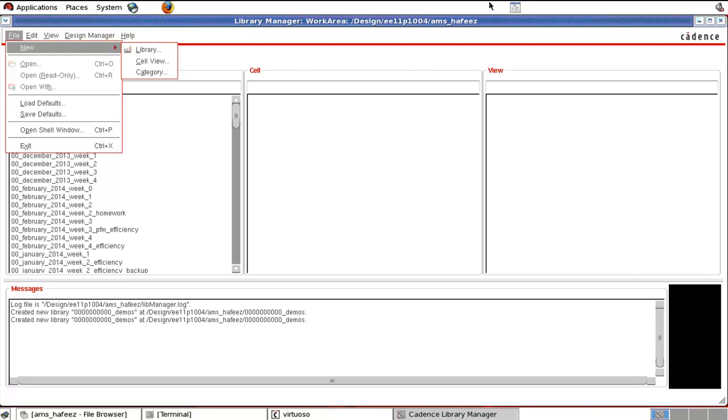When you make a device in schematic, it will not be exactly the same when we make it on silicon. There will be variation due to process. How much it will vary is given by the process corner. So in this video I will demonstrate the process variation of the devices.